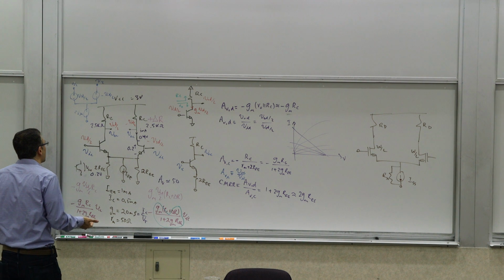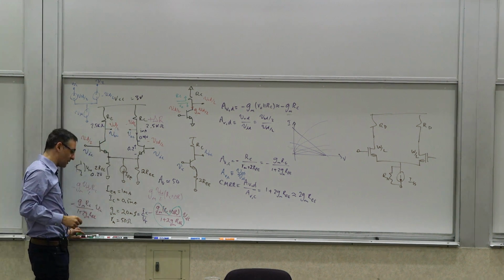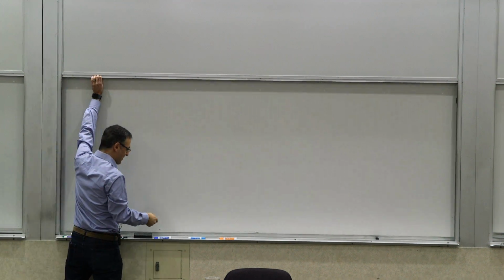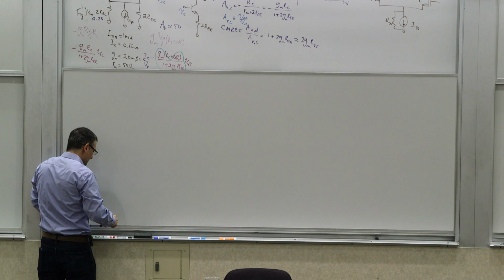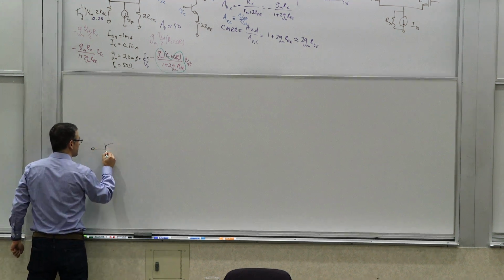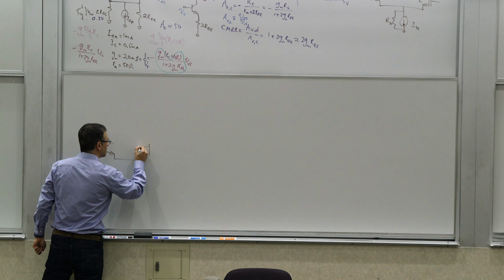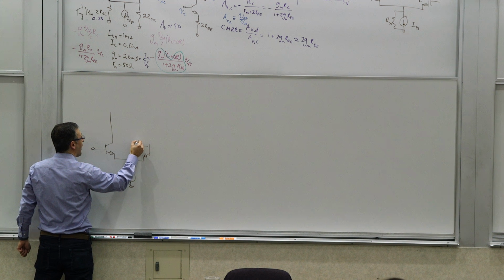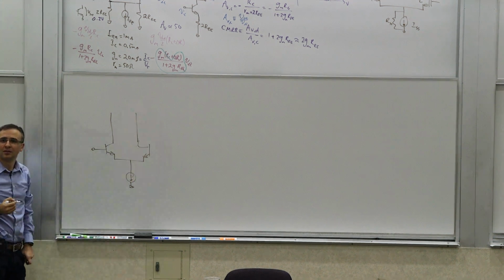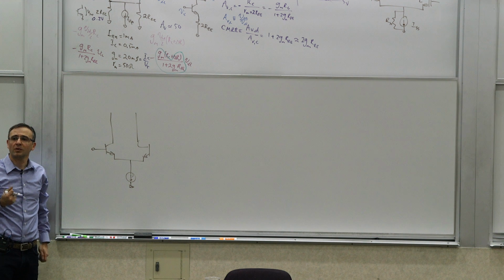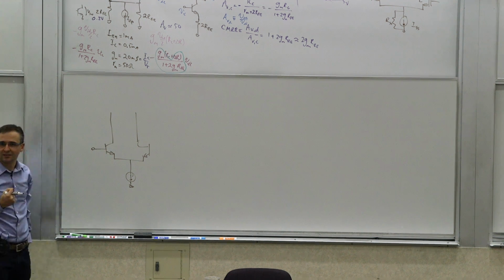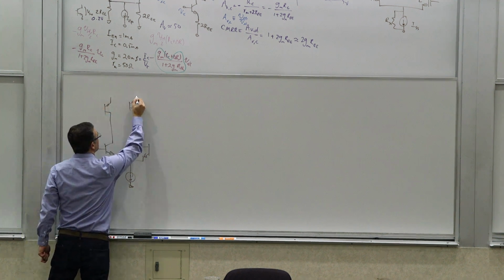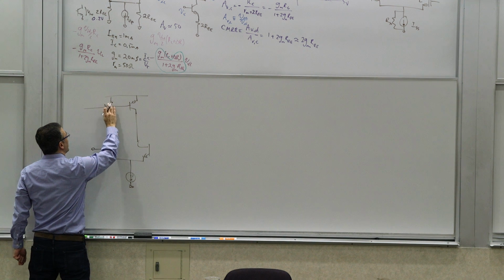And how do we represent a current source? So we basically want to have current sources here, the same way that we did it with single-ended stages, right? Because this is not fundamentally different. This is the same thing. So if you think about this stage, and we can do it in MOSFET and bipolar, and we'll do the MOSFET shortly, I want current sources here as load. But what kind of current source do you want? You want something that can source current, and that would be a PNP in bipolars, or it would be a PFET in MOSFETs. So you can actually make a current source.